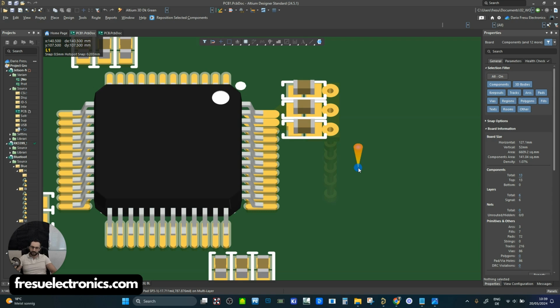Okay, so what is now the strategy that we have to really optimize this power delivery network? How are we going to calculate this target impedance, how are we going to select the impedance that we are allowed to have in our system? To select the target impedance that we want to have in the power delivery network, what we can do is check what is the voltage allowed by the IC that we're using. So what is the maximum voltage drop that we can have in our IC? And then by using this voltage, we can divide it by the transient current of the circuit that we calculated before. And this will give us the impedance.